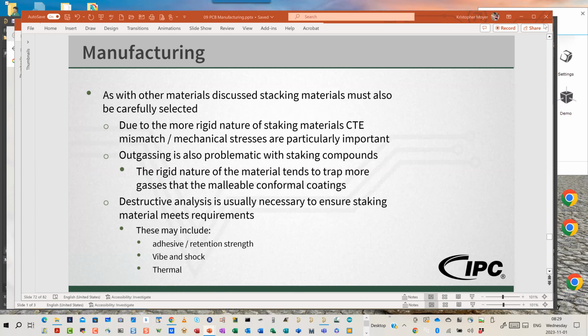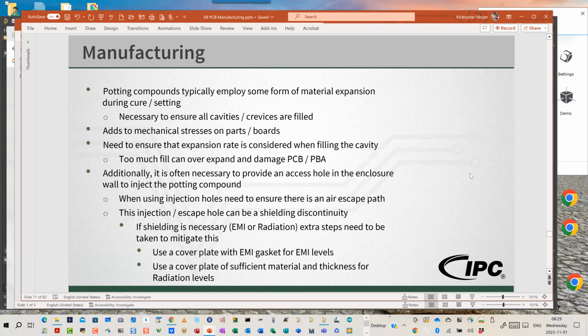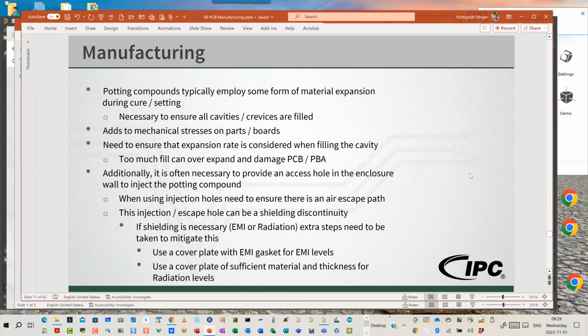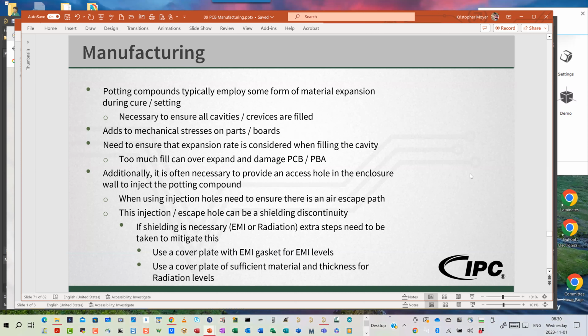Just one point related to coating, for a project related to RF, it's necessary, there is some problem related to the electrical material. If you use some protector for the PCB like silicone or coating, you can alter the dielectric of the surface. So yeah, you need to be careful.